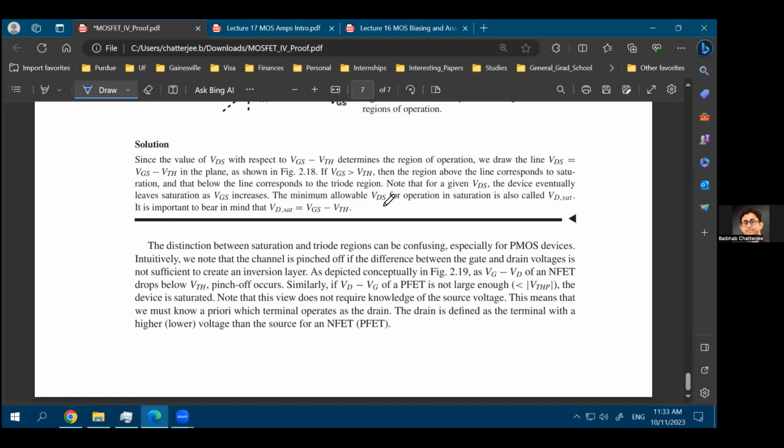In saturation region, you usually have gm times Rout to be much more than 1, usually in the range of 20 or 30. So you get a voltage gain of 20 or 30 times. But in triode region, this gm times Rout is less than 1, so you do not get any voltage gain. Like it stays stable. Yeah, that could be a particular case where the voltage gain was equal to 1, but it is also possible you get a voltage gain of less than 1, depending on the value of gm and Rout.